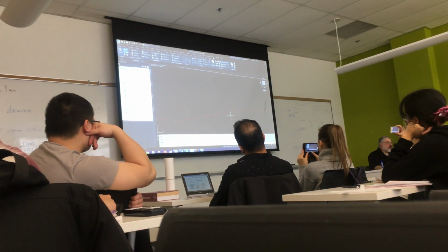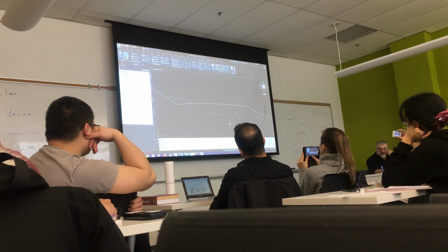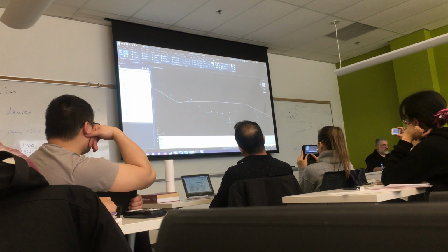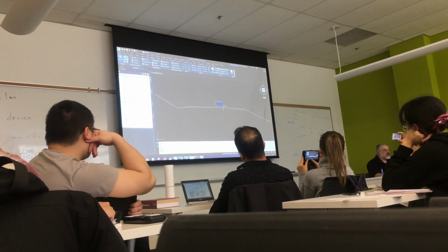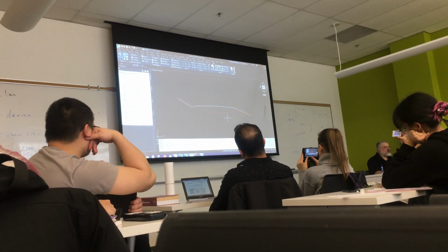Now, I'm not going to bother you with the topsoil depth, right? I'm going to assume this is already stripped. Keep it simple. Okay? So it's already stripped, and this is the pre-grade. Remember, do not include your construction material. How much cut, how much fill?